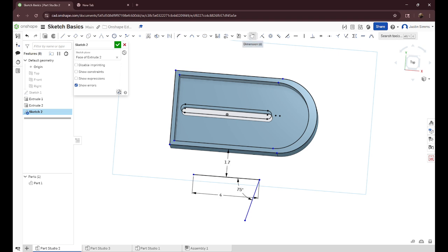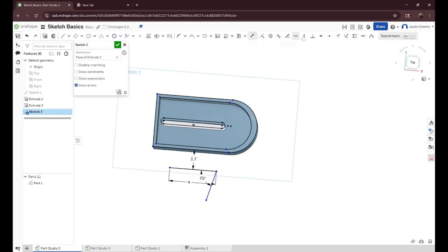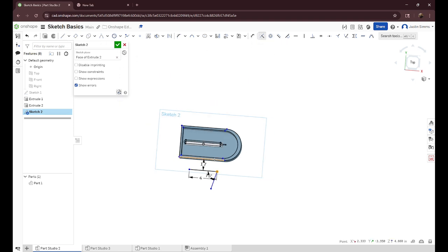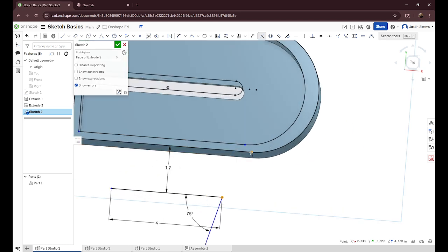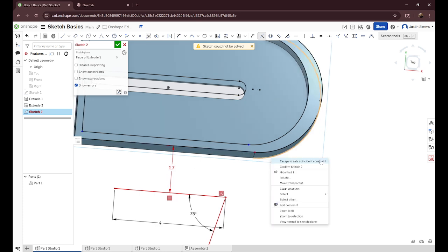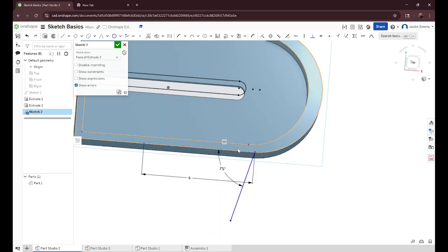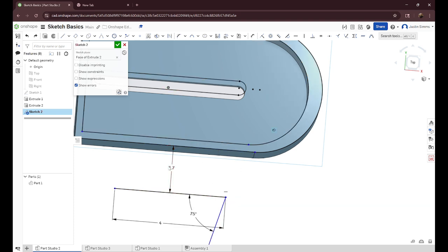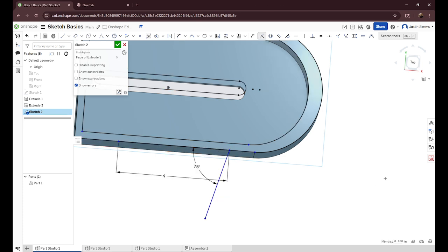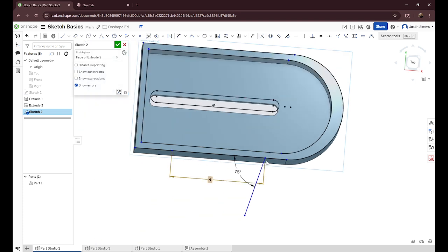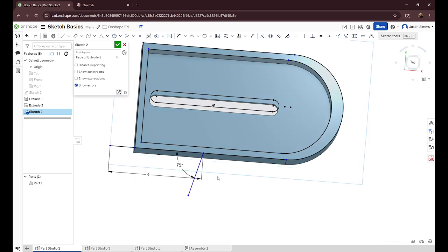And that's probably the most important sketch constraint. And then the rest of these are how you connect everything together. So the coincident will just make a point either match another point. I forgot I had this dimension. Either match another point, or if I go back and delete this, match a line. So whenever it's on a line, it's like the infinite line. So not just the line segment, but it can be anywhere on that path of the line.